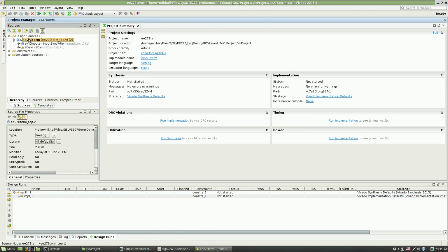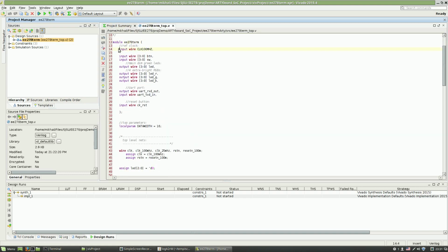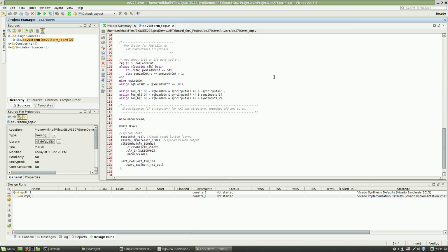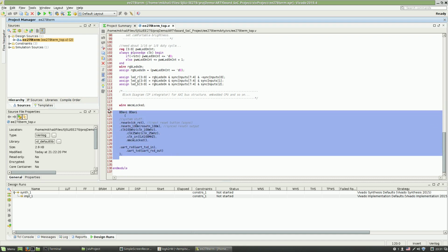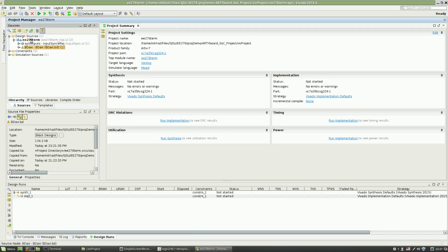As you can see, there is a top file. This thing does very few things. It does a couple of things with the board's LEDs to show that the board is alive. And most importantly, it instantiates the SoC block diagram implementing the SoC system. We will look at it a bit later. But you can see the block diagram file as an instance in the top file.